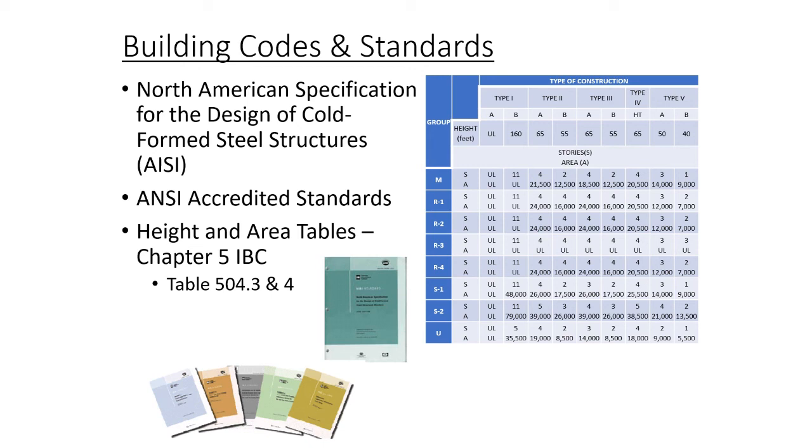This is further modified based on the intended occupancy of the building. Examples of building occupancy include residential, building assembly, healthcare, and education. The tables also take into account if the building is made up of combustible or non-combustible materials, and if the building is to be considered sprinklered.